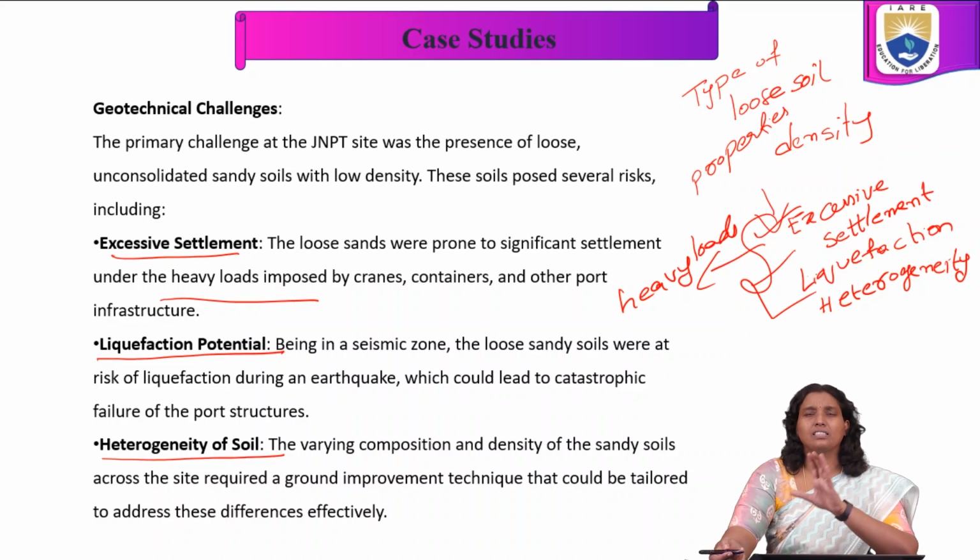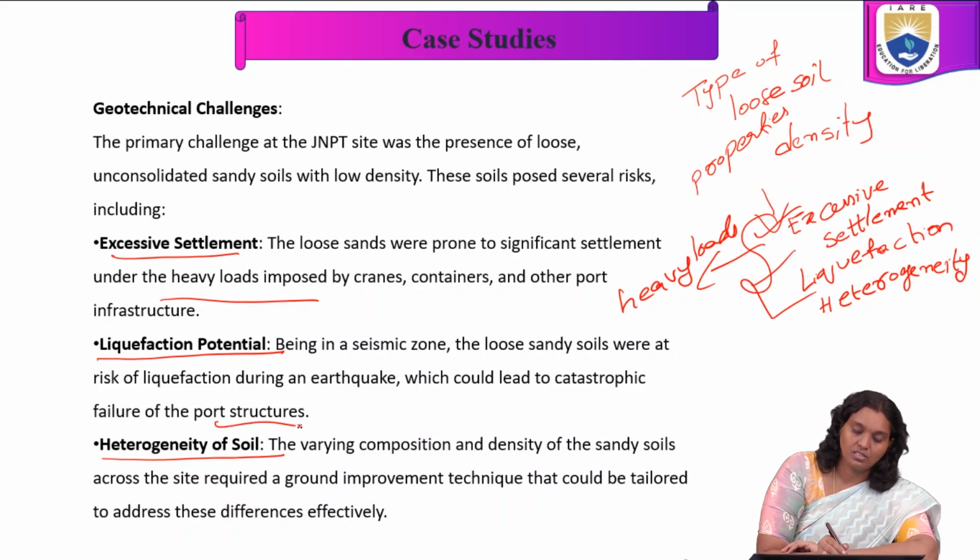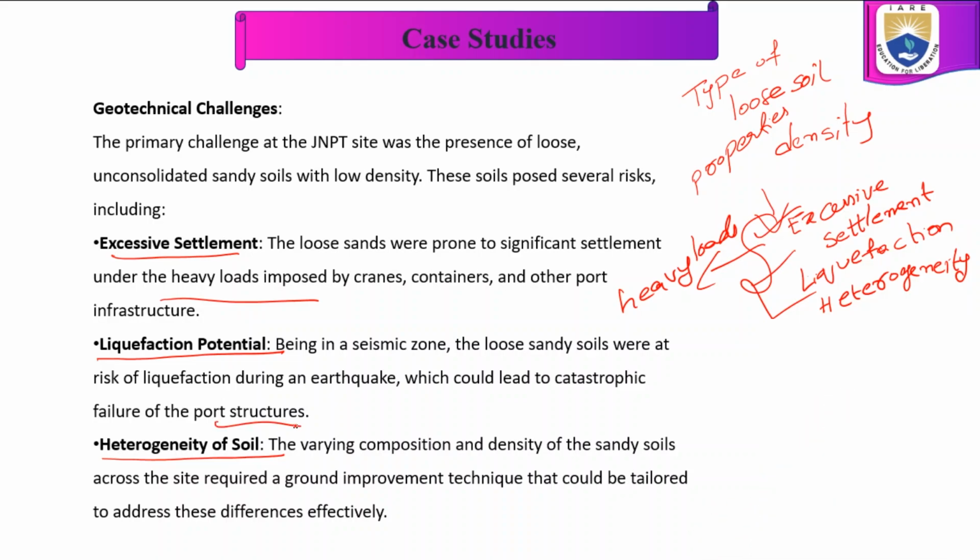The Mumbai area comes under an earthquake zone, a seismic zone, and that too with sandy soils. There is a risk of liquefaction during an earthquake. Whenever a seismic wave comes, it is going to liquefy because of the silt and these loose soils. They allow these seismic waves. It is going to liquefy, which could lead to the catastrophic failure of the port structure. So it affects.